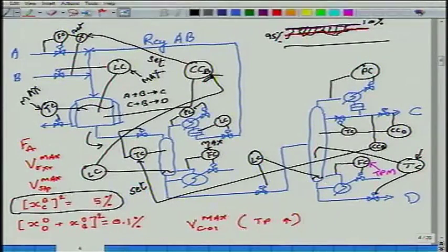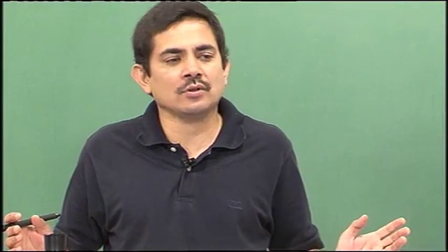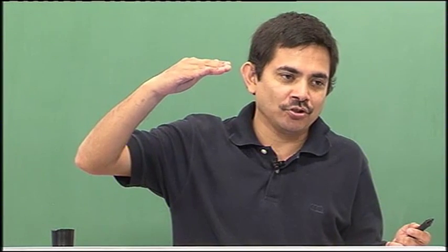Okay. Now the instruction from above is max it out. Drive the car at maximum throughput, maximum throttle. So you are supposed to press the gas to the end, right? So I keep increasing the throughput manipulator set point. Ultimately, what will happen? In response to this increase in throughput manipulator set point, my composition set point for B will keep going up, right, until throughput manipulator reaches max boil up. Yes or no?